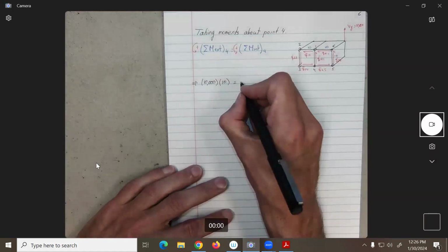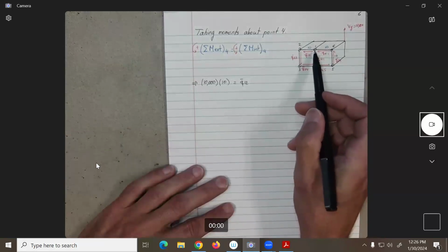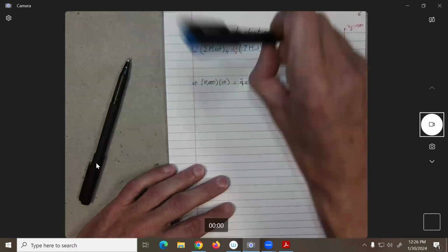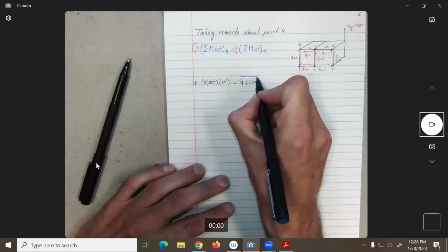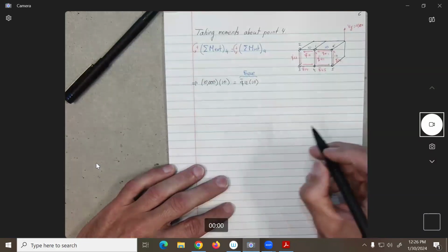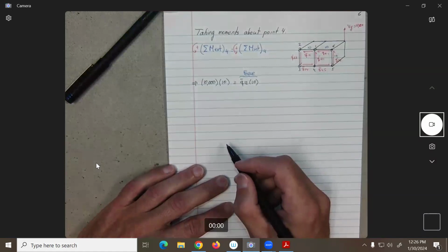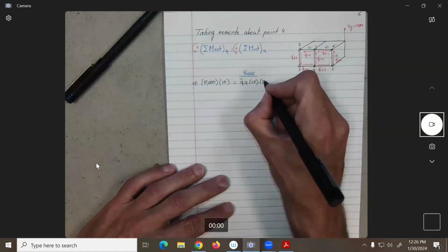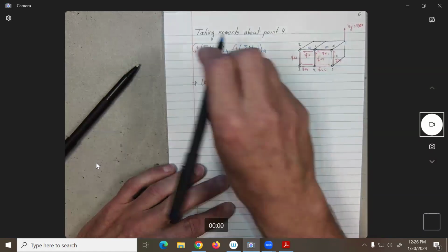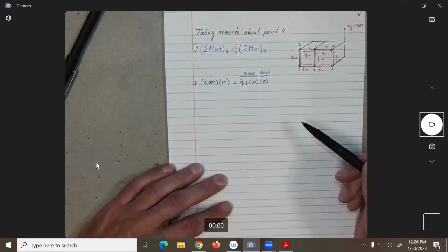Here now, this should be equal to what? If this is going in this direction, and it is the opposite direction, the value of the force should be equal to what? Q12 times 10. What will be the arm? What is the distance between 1, 2, and 4? 10 will be the arm, no? Correct? And if this is positive, we will go also counterclockwise, no? So we create a positive moment.